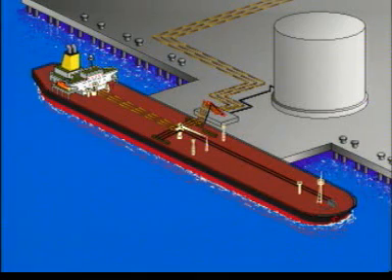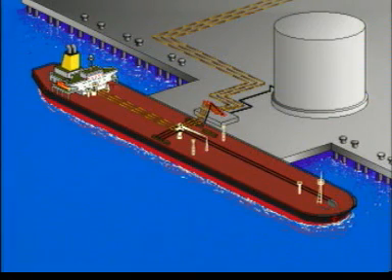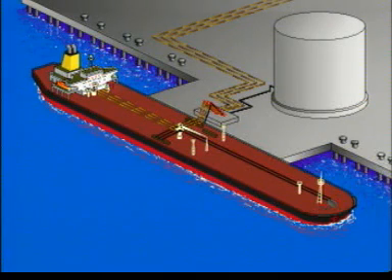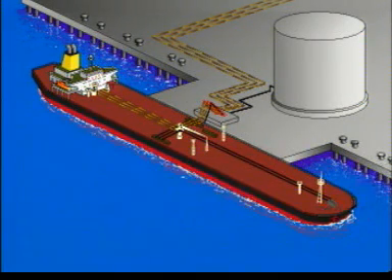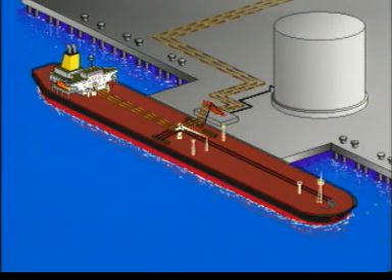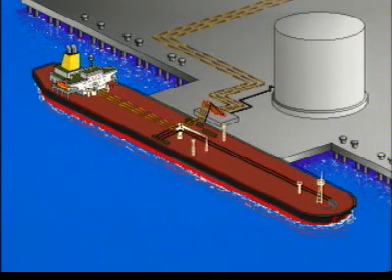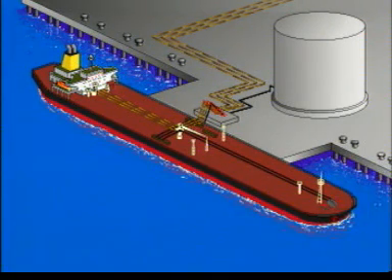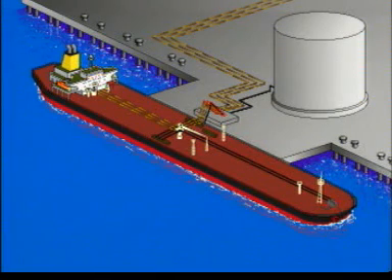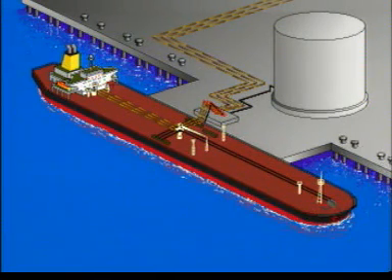The volumes given by the ullage tables are seldom exact. When you load the vessel, you will, most of the time, experience differences between your own figures and shore figures. Your problem is to take on board a full cargo without overloading nor short-loading the vessel. To be able to do this, you must know the vessel's experience factor. Different companies and charterers use slightly different methods to compute this factor. Principally, it is the ratio between ships and shore figures obtained by comparing the results of a number of actual loading operations.